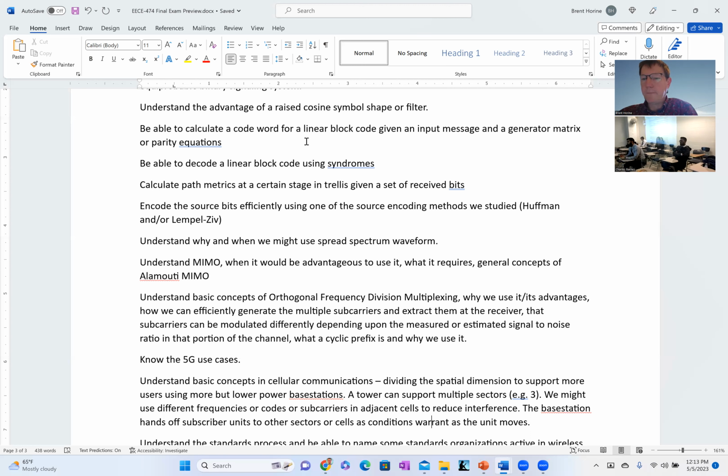You could find the H transpose from the generator matrix, right? But you may be given the H transpose, so you're multiplying r times that H transpose. That produces a syndrome, right? And that syndrome, in the previous cases, was 3 bits long, right? And that's again a consequence of the size of the code rate, that type of thing, right?